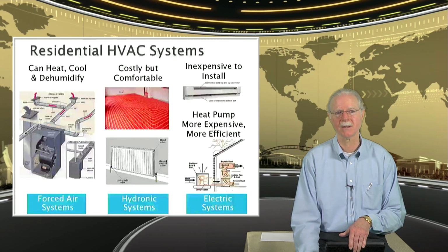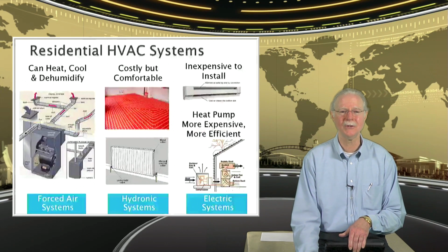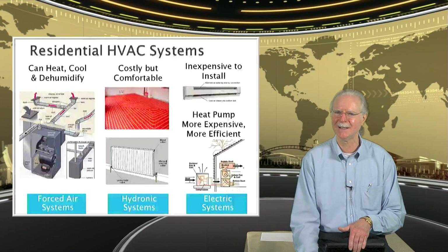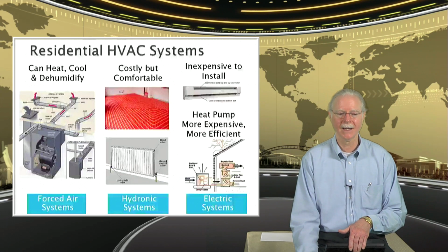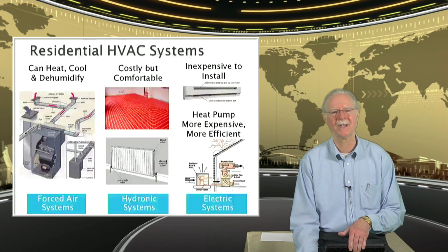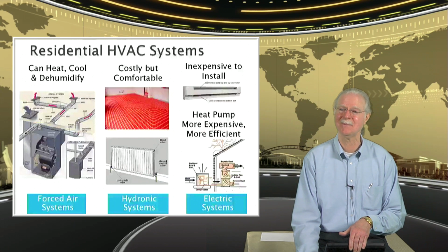in the older systems. Now, it actually does bring up an interesting point, and that is, if you are looking at this kind of system as a retrofit, how many options do you have? Not very many, because you can't really do a retrofit unless you intend to be replacing floor systems anyway. It's a real challenge. Even if you're on a wood floor, and you can do a hydronic system on a wood floor, you still are in a situation where you have to completely replace what was there before and or add to the top of the existing system.